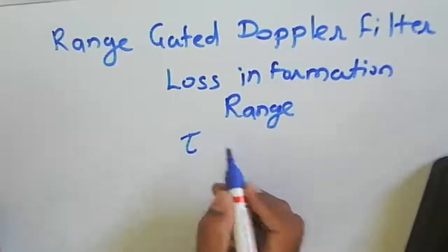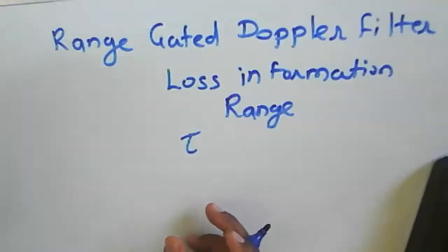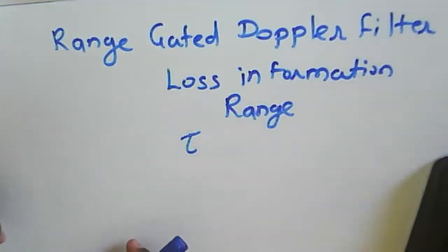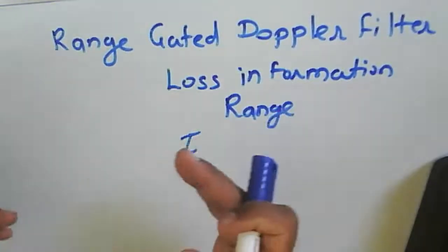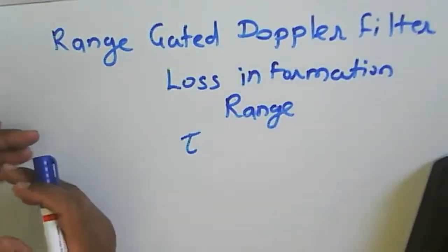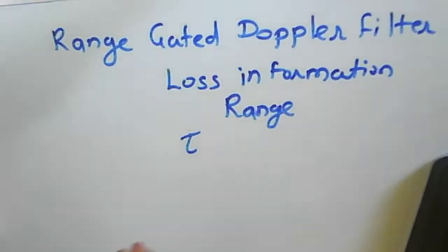because we know the time period for the round trip time. And that round trip time from the moving target, that information we are losing there. Again, the signal from the moving target as well as that from a stationary clutter, when it reaches there, both the signals are collapsing, so there will be a collapsing loss.